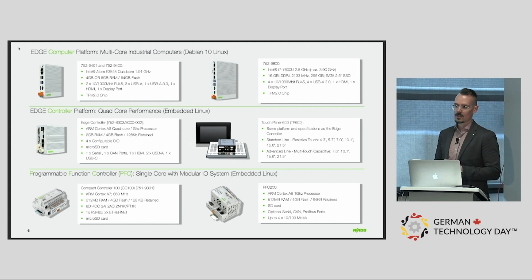with Docker. Docker is basically like a virtualization platform, but instead of virtualizing a whole operating system, it just allows you to package and install applications to your device. That's important because it allows us to install a variety of different third-party software onto our device. It enables something that was traditionally PLC and only ran PLC applications to now run a bunch of third-party software in conjunction with a PLC application or completely separate of a PLC application.